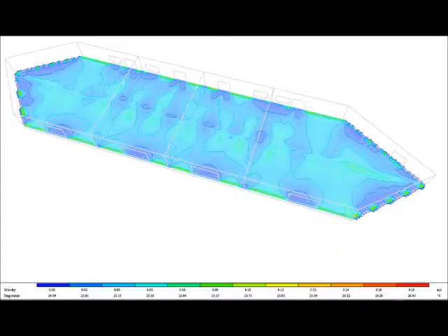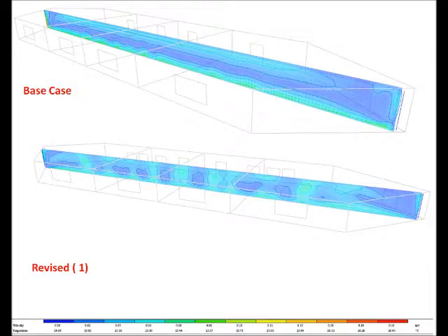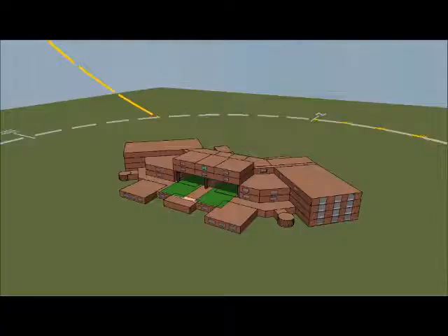The indoor air temperature records a drop by 1.3 degrees Celsius to be 25.32 degrees Celsius, while the velocity increased to 0.06 meter per second. But the air distribution shows a high improvement, as shown in the cross section, since additional openings were added to the courtyard site. For further enhancement, we extended the green surface and re-evaluated the indoor spaces at the same conditions.